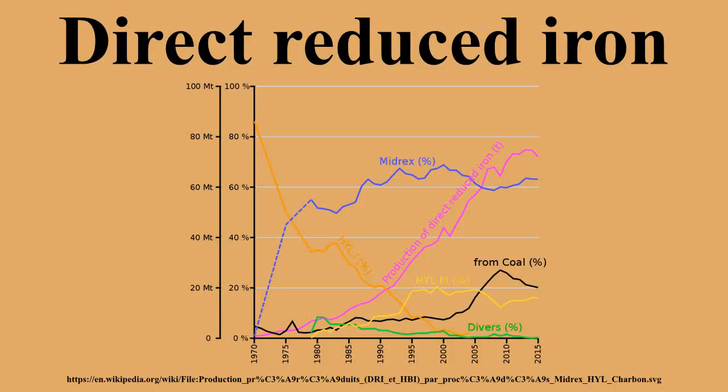The direct reduction process is comparatively energy efficient. Steel made using DRI requires significantly less coal, in that a traditional blast furnace is not needed. DRI is most commonly made into steel with electric arc furnaces, to take advantage of the latent heat produced by the DRI product. In modern times, direct reduction processes have been developed to specifically overcome difficulties of conventional blast furnaces.